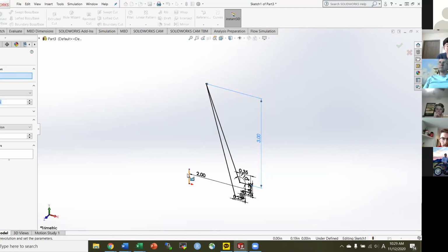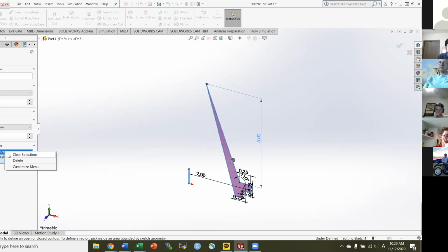Set the axis of rotation again. Select the contour. And then if you misclick something, for example, I clicked on the line 1, you can click on that option and then you can click delete. Then it'll delete it for you. So I have the line as the axis of revolution and then the contour. And if I click on OK,